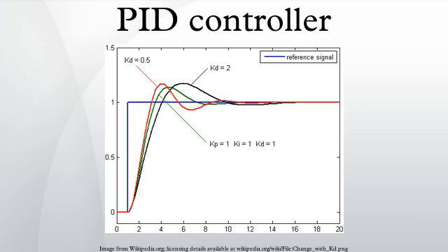The ultimate gain and the oscillation period are used to set the gains as shown. These gains apply to the ideal, parallel form of the PID controller. When applied to the standard PID form, the integral and derivative time parameters are only dependent on the oscillation period. Please see the section Alternative nomenclature and PID forms.